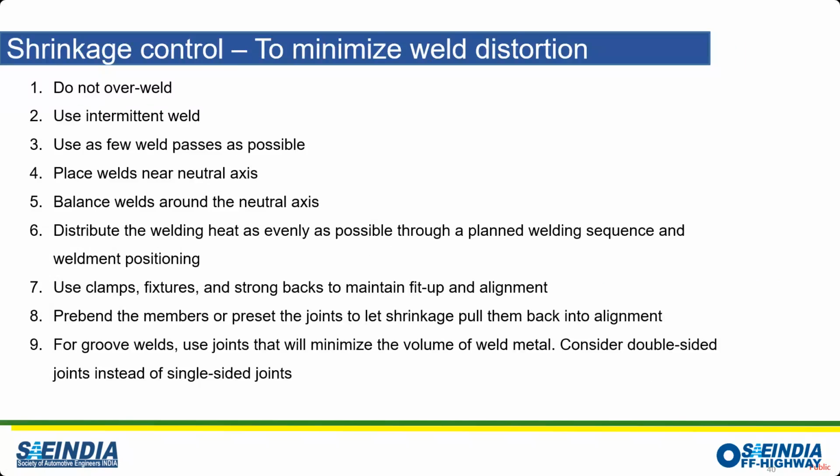While you're actually making the structure, usually what happens is we design the structure to have the connections wherever needed, and as I explained earlier, you are going to keep the connections at a place where your load is going through the members and not through the weld. So even though we are designing all those things very judiciously, in actual operation, when you are putting all that heat into the metal, in the microstructure of that metal there will be a shrinkage which will happen. That would actually distort the assembly.